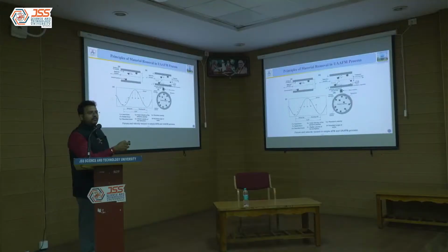So what is that change? It is explained here in the principles of material removal. This is a cylindrical workpiece, and our target is to finish the internal geometry of the cylindrical workpiece. When we pump the media to and fro, some abrasive particles are active and some are inactive.